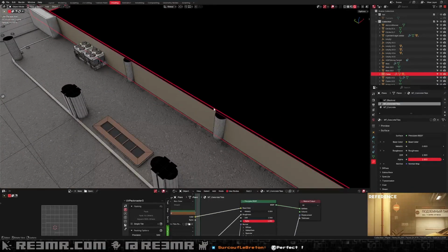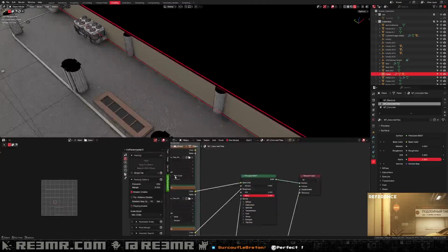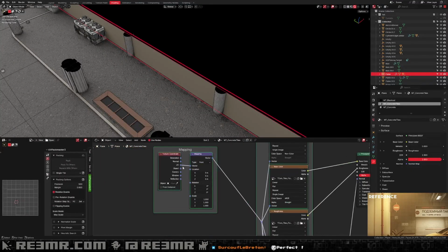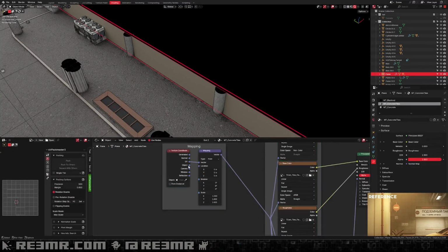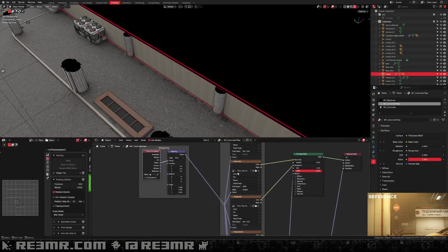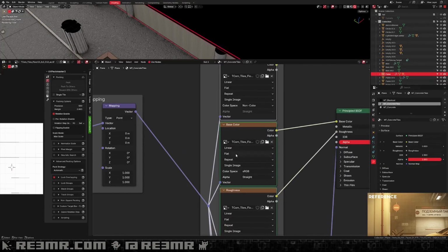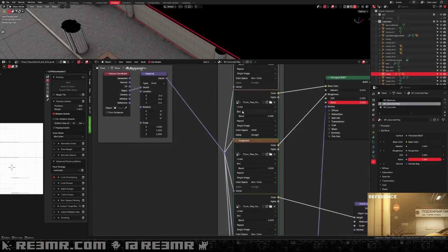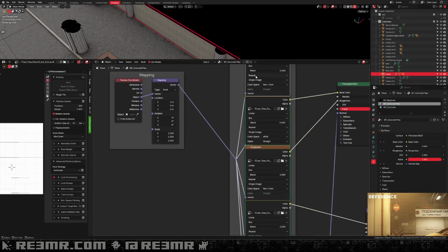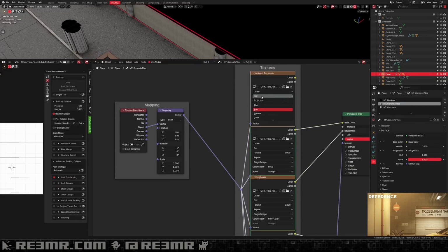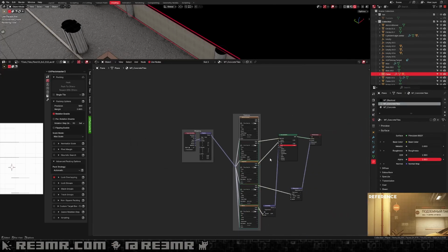And it's not gonna work because it's using the UV projection right now. So it's also something we have to change. Change that to object here. And then all of these also need to have the projection changed to box. There is a way to do this quickly. And I thought I'd forgotten about it, but apparently I did not. So what you do is you go into one of them, hold down the Alt key and just pick the option and all of them will change. So it's less work that way.